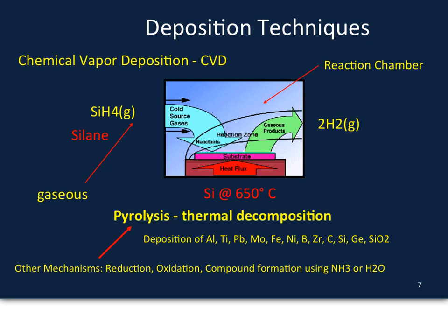And so again, here's an example of one of the more common deposition techniques, which is called chemical vapor deposition. The idea here is that we have this substrate onto which we want to put a thin film of a new material. What happens in chemical vapor deposition is that you use a gas phase precursor of the element to be deposited.